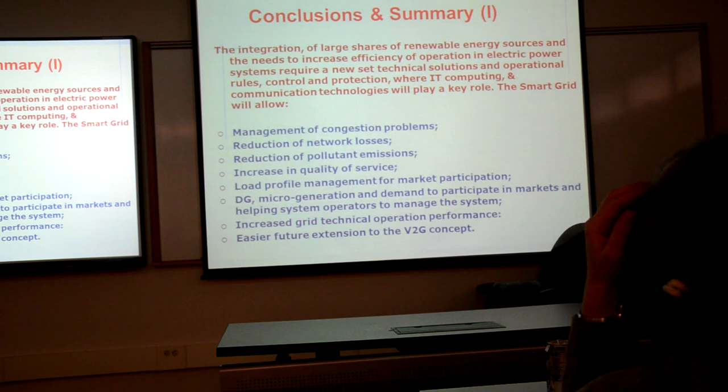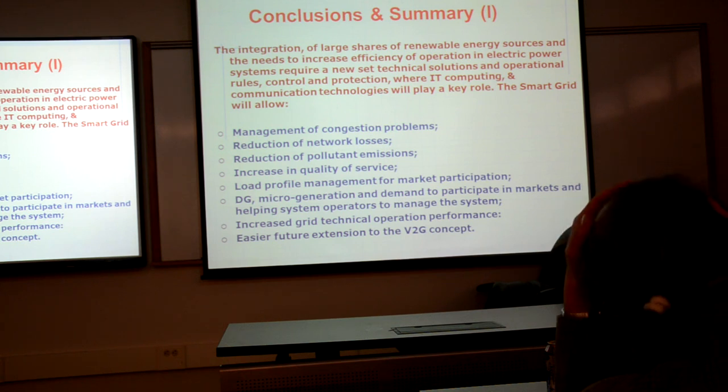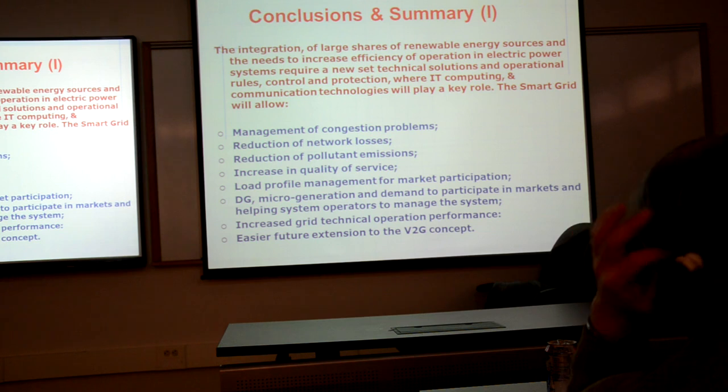Right now, a lot of systems that are sold commercially for small grids, if the grid goes away, they should shut down. Yes. And that's for safety. Yes. Because they don't have the ability to connect and disconnect safely. Yes, that is. Plus, we have issues with most of the circuit breakers being designed for the present-day grid, not for a grid that is operated at much lower voltage, where you have a much lower difference.